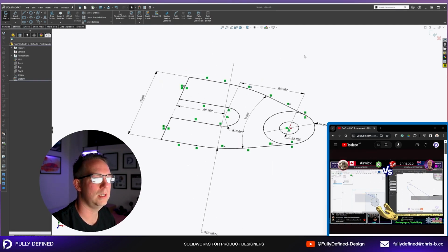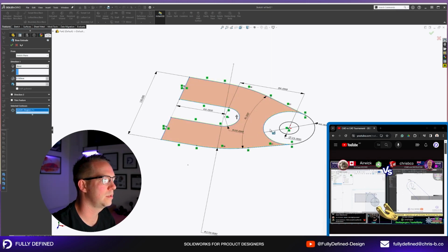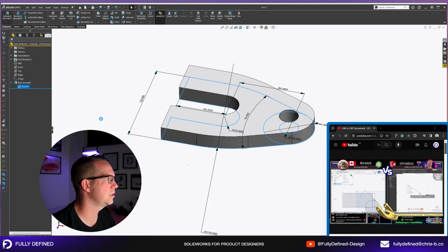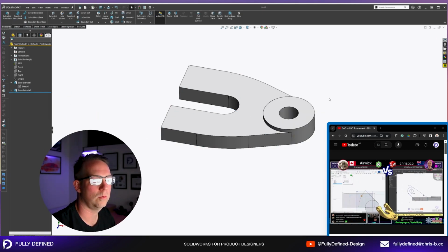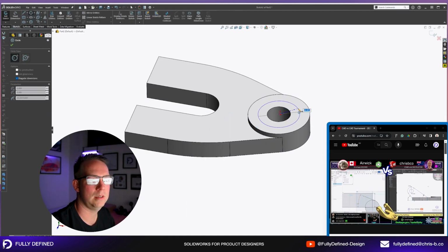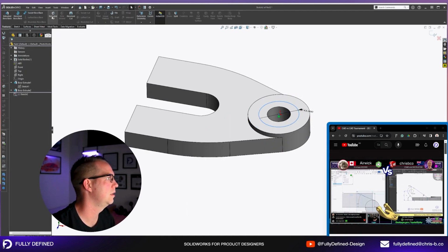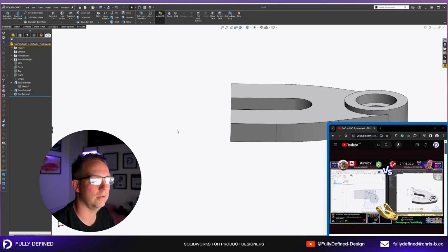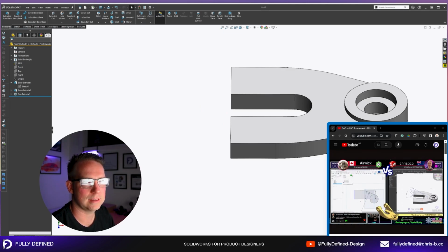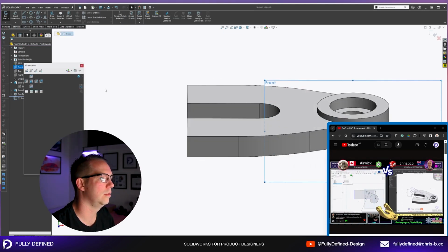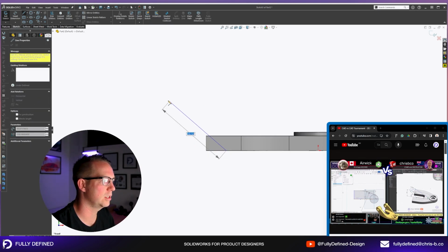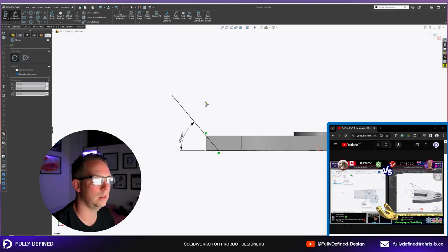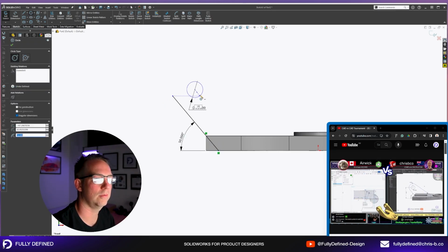And then what I would have done is use contours to go up that full height, 20 mil, and then use that section of the front to go up 25. And while I'm here, I can get that counter bore done, 43 down 10. Okay, so now it's all about that angle, that cutoff there. So if I had have done it correctly now, I can see that that 66 is the top. So from my front view, what I should be drawing is this profile, and I can actually go through that point. So this is where I failed last time. So I get that point in, and the rest of it should be pretty straightforward from there, I think.